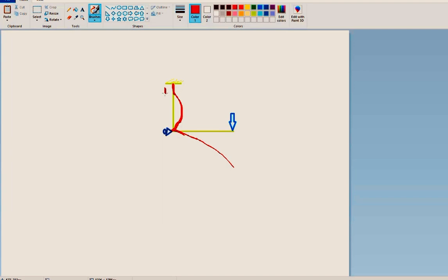So if you see here, tension is coming here, tension is this side, and tension is this side for this structure when the force is applied like this. So if we draw the bending moment diagram for this one, same, for this beam, this is the force, and the distance goes increasing this way. So the moment will be going like this, varying linearly. This is the moment diagram, this is the moment line. And at this point for this column, the force into distance is the same. So the moment will be the same moment value. Whatever this moment is coming, the same moment value is coming.